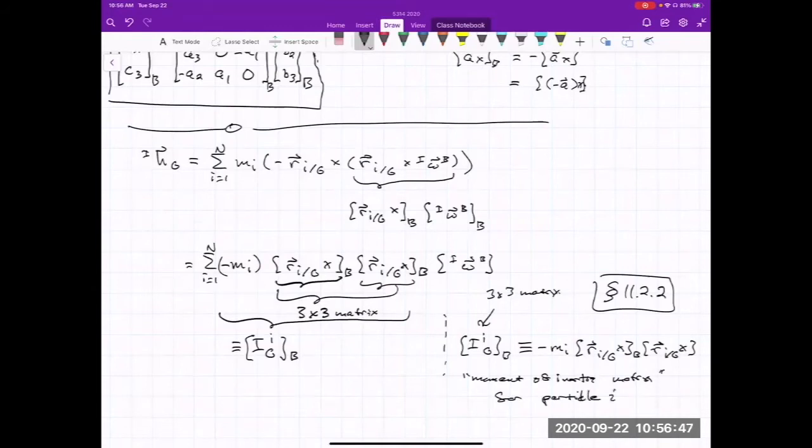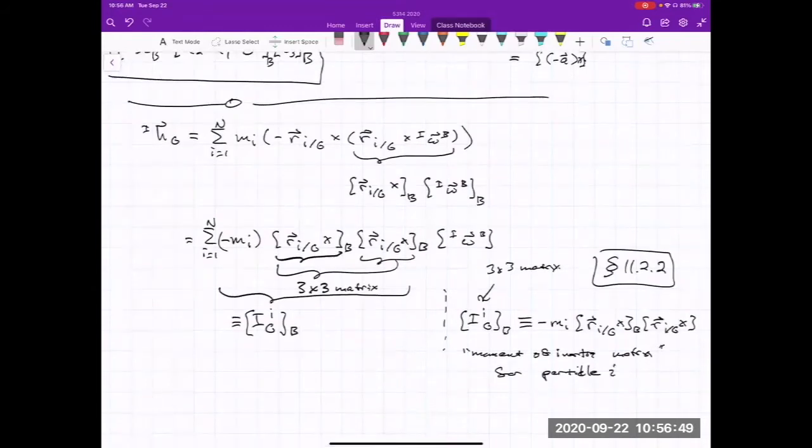Of course we have a sum of these, I_G equals the sum from 1 to n, the number of particles, of I_G superscript i, B. And so we have this summation of things that do not depend on omega, all times the vector omega. For consistency, I need to write that over here, we're writing the angular momentum vector also in terms of the B frame.